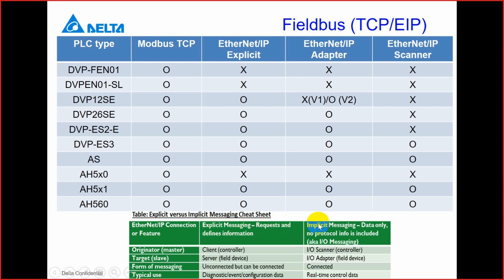That means with implicit you can pull the data very frequently, but with SDO, every time you want to get the data, you have to send out the command. This one you can consider more for important device information that might affect the device dropping or something else.